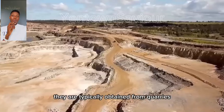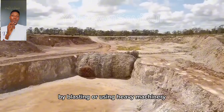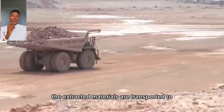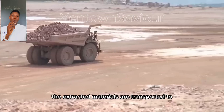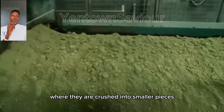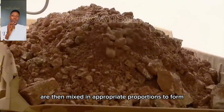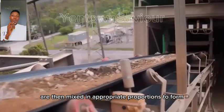They are typically obtained from quarries by blasting or using heavy machinery to extract them from the Earth's crust. The extracted materials are transported to the crushing plant, where they are crushed into smaller pieces. The crushed limestone and clay are then mixed in appropriate proportions to form a raw meal.